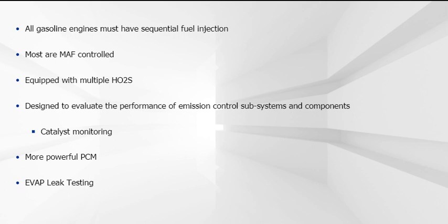In addition, the evaporative emission system contains devices specifically designed for conducting leak and flow tests. With OBD2, trouble codes are not based solely on gross failures, as was the case with OBD1. That's because OBD2 is designed to turn on the malfunction indicator lamp, or MIL, when the performance of an emission-related system or component, or catalyst, has deteriorated, rather than wait until it stops working altogether.